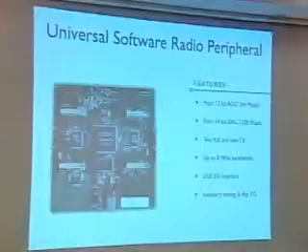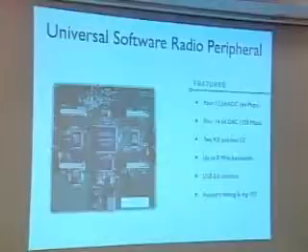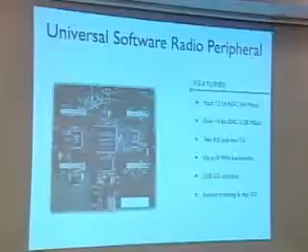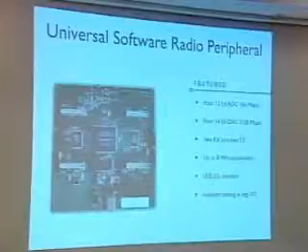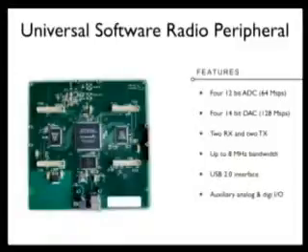In addition to that, it has the main analog-to-digital and digital-to-analog converters. That's what you see on the two sides of the board. The two white connectors are where you mount the RF front-end boards. You can see there is RXA, RXB, TXA, and TXB. It means that it can take two receivers and two transmitters and use them at the same time. Okay, two transceivers. The only requirement there is that they have to share the 8 megahertz of bandwidth. So it's still pretty good.